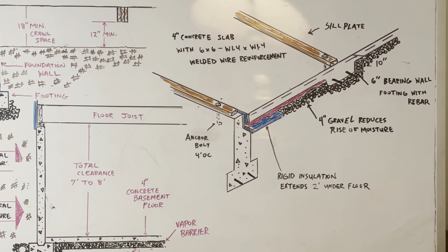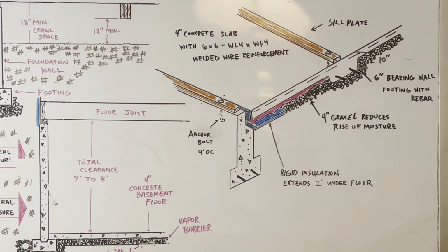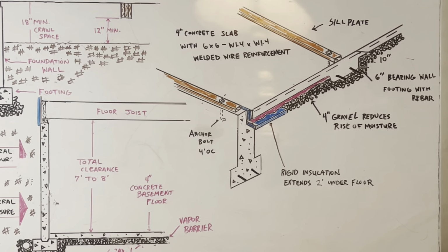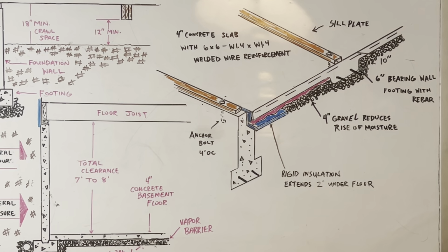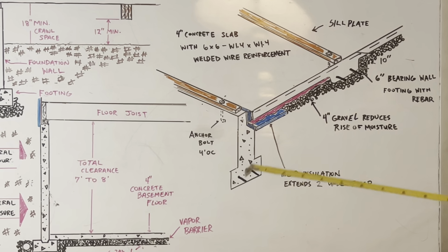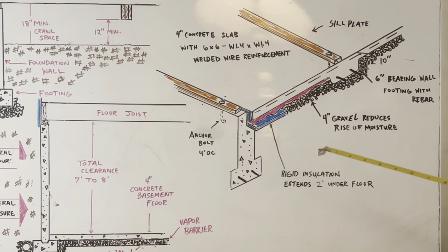Now, in warmer climates, concrete for the walls and floor is placed at the same time. Okay, that's called a monolithic pour, or a monolithic construction. Okay, the foundation and the floor slabs are one unit. Now, I don't have that type of slab drawing right here, okay? Which it would be a monolithic pour. Okay, so